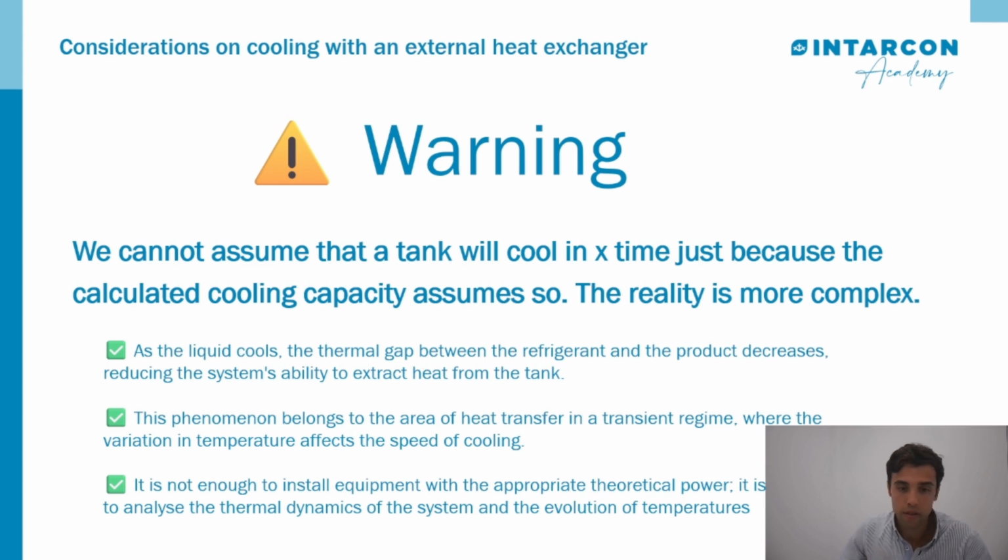As the liquid cools, the thermal gap between the refrigerant and the product decreases, reducing the system's ability to extract heat from the tank. This is the case that we are going to dive into. This phenomenon belongs to the area of heat transfer in a transient regime, where the variation in temperature affects the speed of cooling.